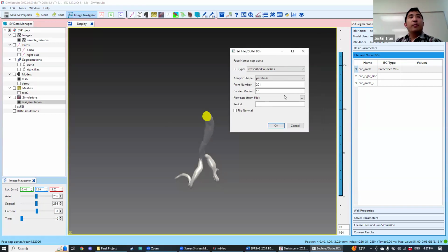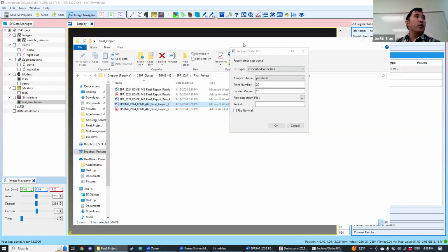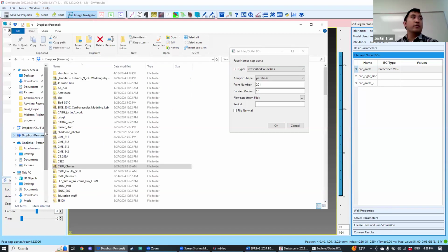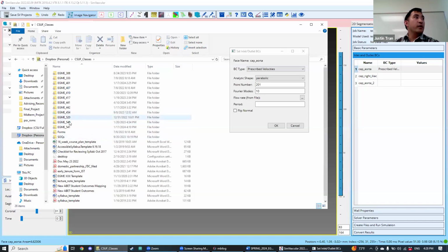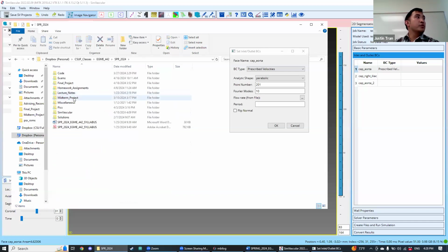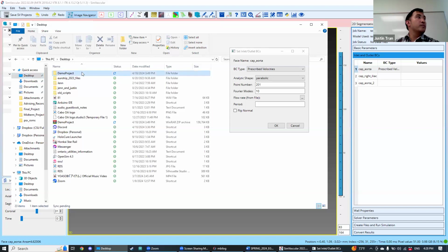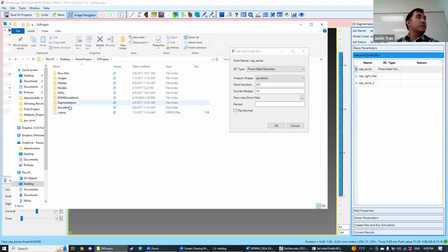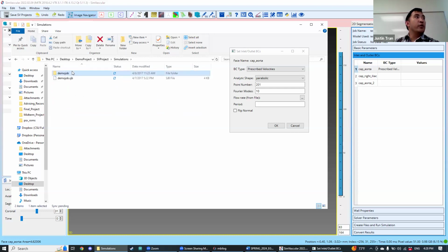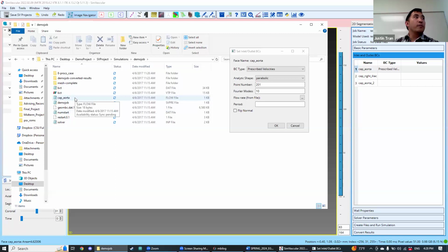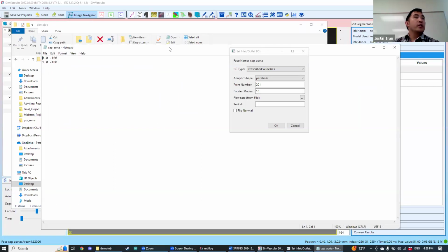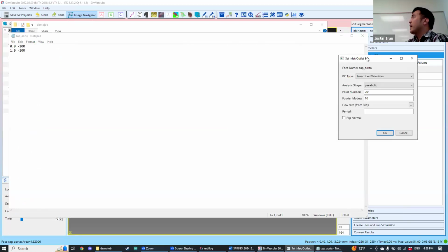All right. The next thing we need to upload here is what's called a flow rate file. If you go to Canvas, you'll see that I've uploaded an additional file under week 13. I can't open it from there because my computer is out of memory, but I have it on the desktop. The file is called capaorta.flow. If you double click on that file, you'll see that it's just a simple text file. If it's asking you what program to open it in, you can just open it up in Notepad.